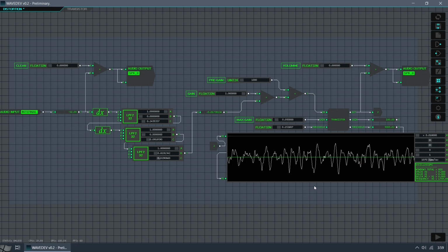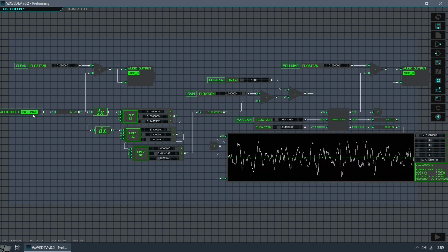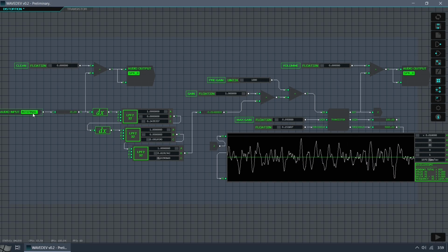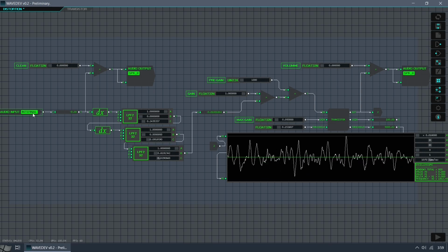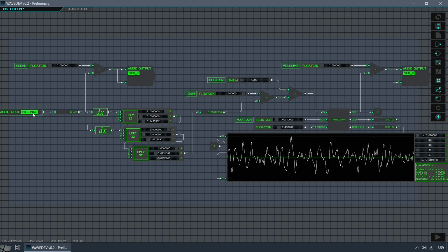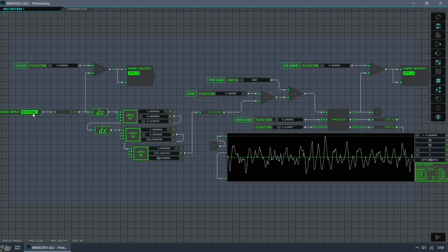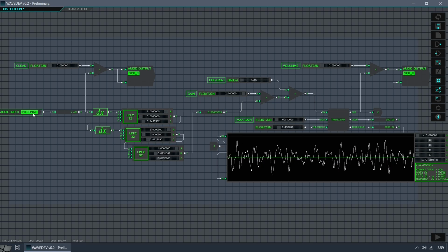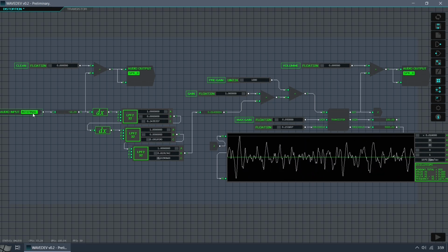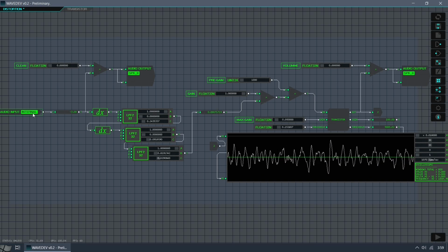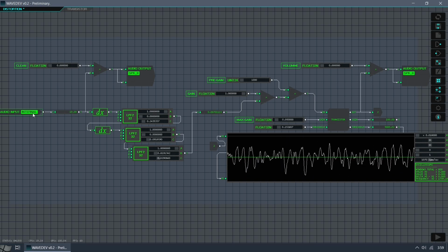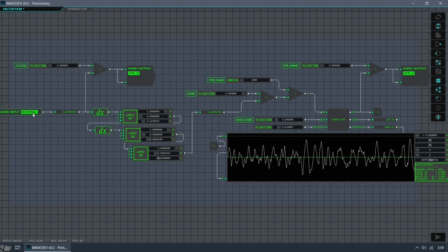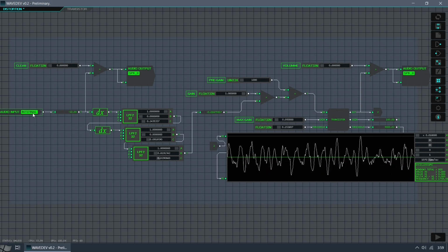At this moment, I am connecting my guitar to the microphone input of a laptop. This is the worst option you have available to implement this algorithm, and also for any other high-end effects processing software. So the next logical option would be to use an audio interface. These interfaces usually have a physical knob for gain control, therefore they have a real preamplifier. Unfortunately, in many cheap audio interfaces, like the one I'll be using in this tutorial, this preamp is very noisy too. Although it is possible to clean up the conversion quite a bit if we use it discreetly.